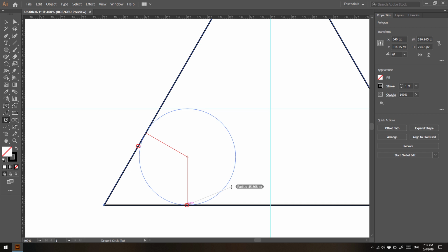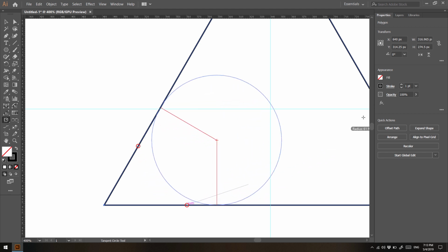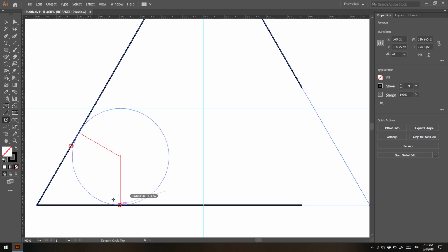And you can do two things. If you hold down the shift, it's going to remove the decimal points. As you can see, sometimes we have just one decimal point, but if you release the shift, the decimal point is going to be 2 or 3. And if you hold down the control, it's going to give you much more control. It's going to increase and decrease the size of the circle gradually, so it becomes much easier for you to eyeball it and select the proper size. I think at this position it is okay. Look at the number, 45.7. I'm going to release it.